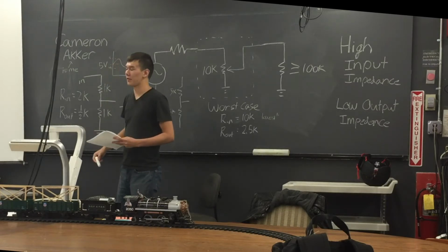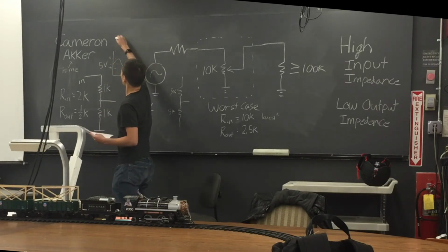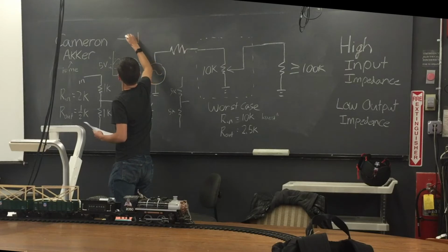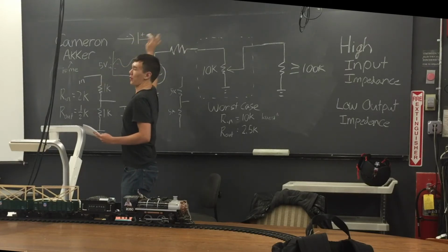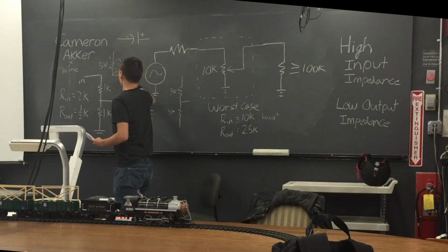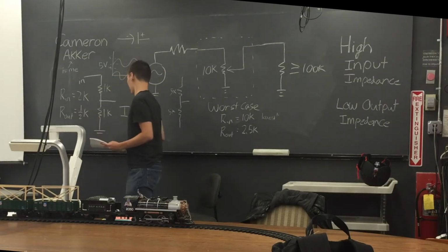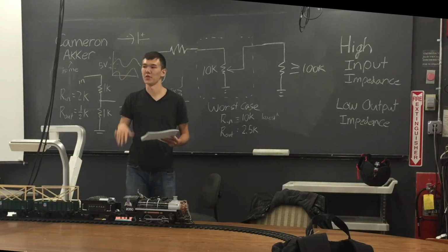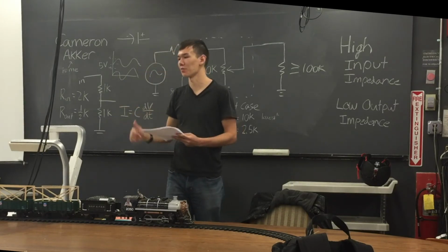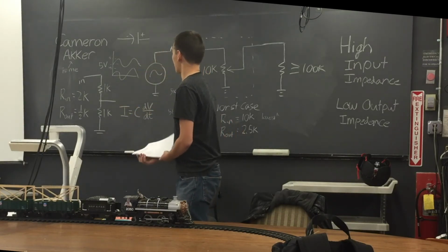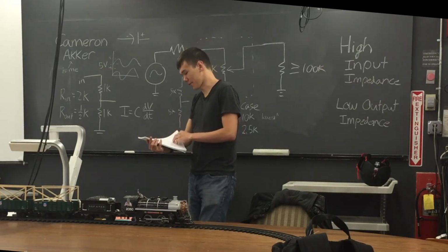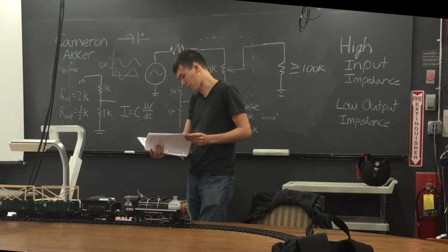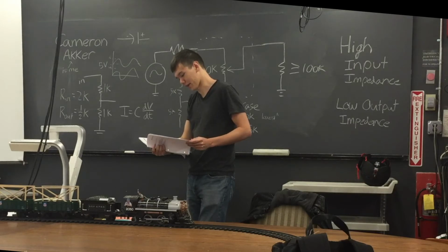Okay. But if you put this through a decoupling cap, just more circuit on the right side, you assume, then it would drop down to centered around 0. So decoupling caps knock out the DC component. That helps in some cases where you want a signal centered around 0. There's a couple of problems that use that. Probably the first homework would have a problem like that.